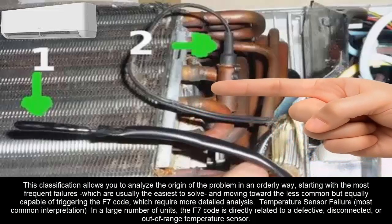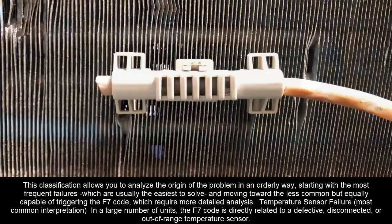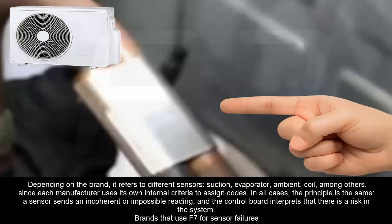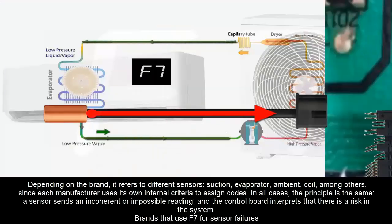Temperature sensor failure, most common interpretation. In a large number of units, the F7 code is directly related to a defective, disconnected, or out-of-range temperature sensor. Depending on the brand, it refers to different sensors: suction, evaporator, ambient, coil, among others, since each manufacturer uses its own internal criteria to assign codes.